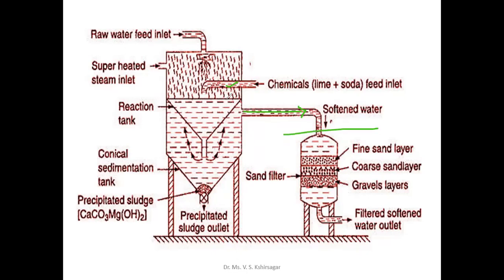Chemicals are added in the water, and time is provided for the chemical reactions. The arrangements are made in such a way that sedimentation can easily be performed here, because we have already done the sedimentation process in a sedimentation tank, but that is for individual particle settling, as well as those particles that can be coagulated with the help of coagulants. But those in a dissolved form are not possible to coagulate. For that purpose, we need to apply such types of methods. That is, one among them is the lime and soda application together.